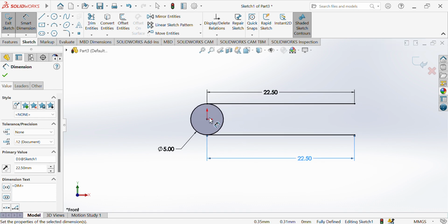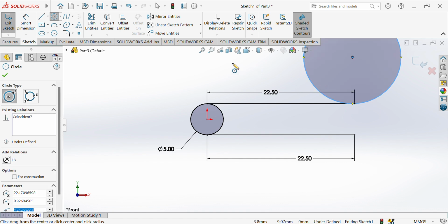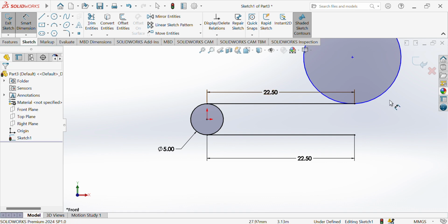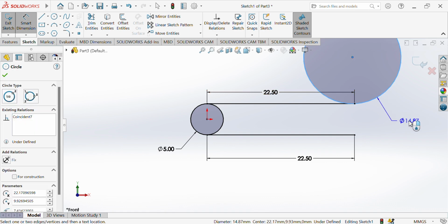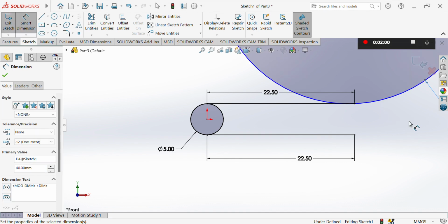The next thing we have is a circle, yes, that's intersecting this line at that point. So let's do this. You can easily do this. Just pick a point here. Now remember I told you that you can make it vertical, so just make it here. So you now do smart dimension. Make this a radius of 20, so that is a diameter of 40. Fit this to screen.